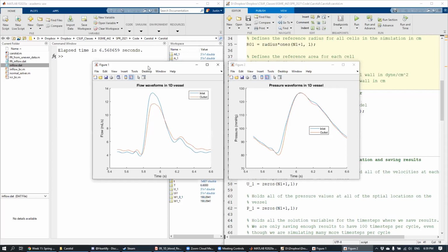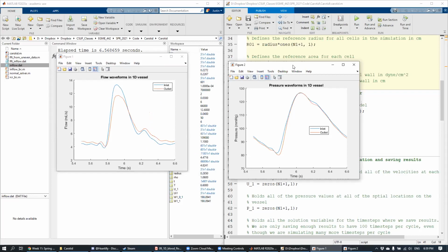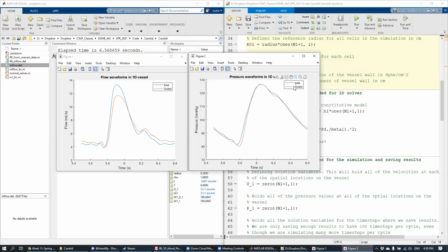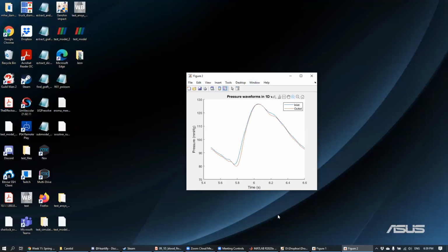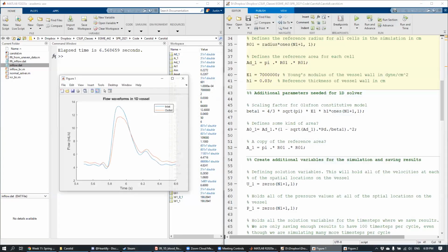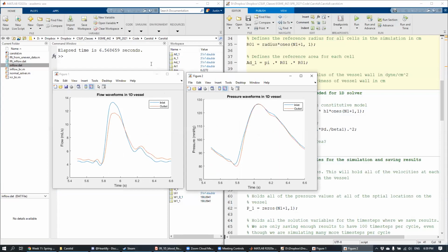And so this is just a simple example because it's just one vessel, right? But even in just this one vessel, due to the 1D equations, we see these really cool, realistic effects that we wouldn't be able to get in LPMs. And with CFD, if you're using rigid walls, you won't be able to see this either, right? These things come very naturally from the 1D equations, and we obtain these simulation results in 6.5 seconds, which is not immediate, but it also doesn't take forever, right?